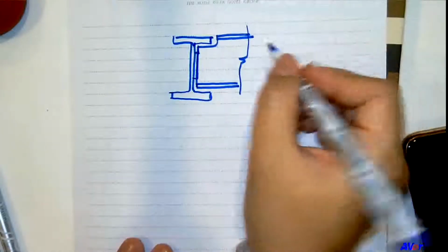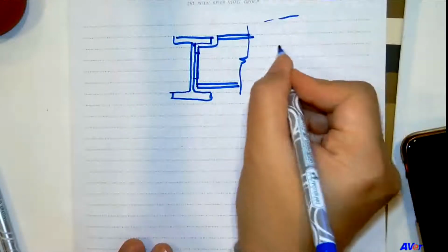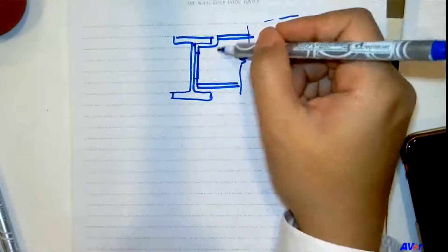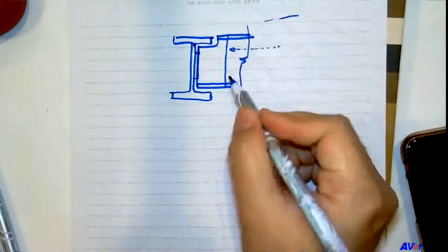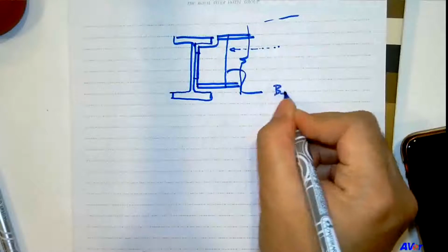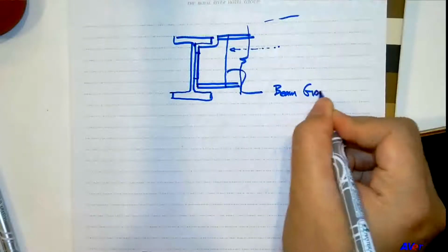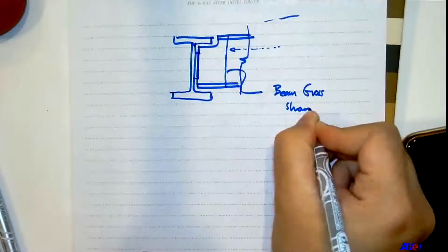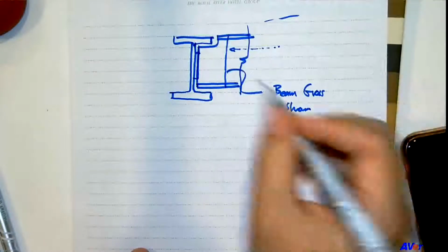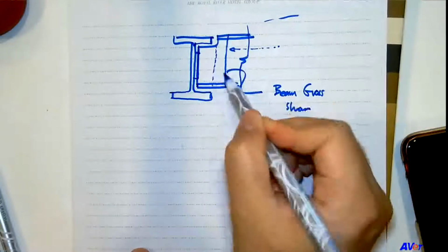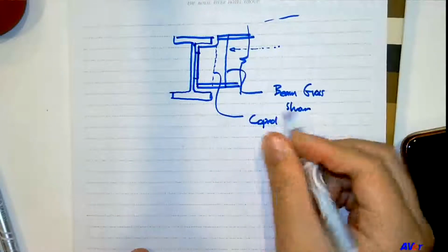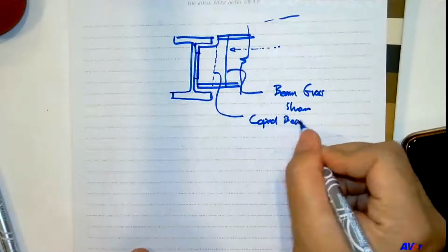So if we follow the load path, say the load somewhere, the shear will come in here. And the first thing you need to consider is the shear of the beam, just to make sure that the beam can carry shear, right? So the first here is beam shear, beam cross shear. It's the first failure that you should check, just to make sure that, okay, no mistake is made when designing the beam. And then you reach this point. So that means you need to check the cope strength, cope beam strength.